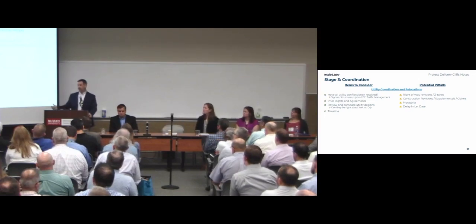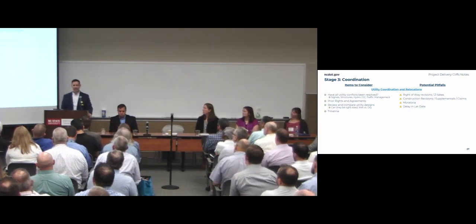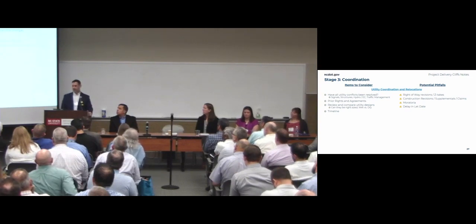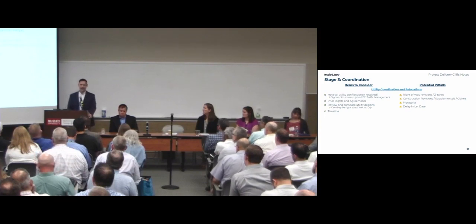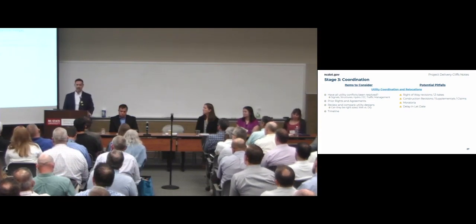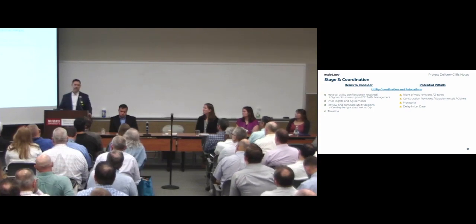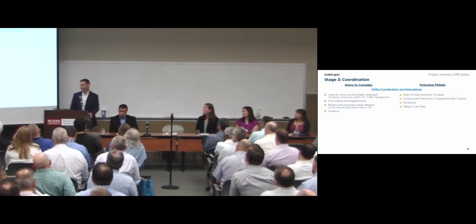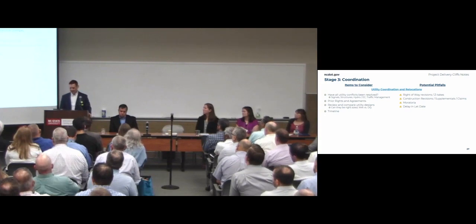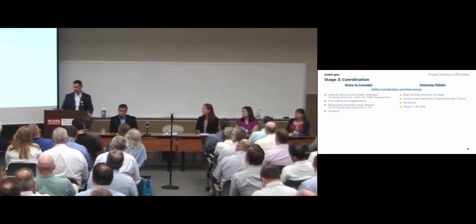And I say there, can they be right-sized? You know, we're not designing the utilities for Duke and these other dry utility owners. But when you get those, look at them and determine, are they asking for too much? Can we reduce that? Are they taking a gas station canopy where we could easily modify it a couple of feet and avoid a major relocation? So look at those things. Don't just accept what they give you. Ask questions. Don't be afraid to ask questions of the utility owners. They may tell you no, but it's worth asking to reduce those impacts down the road.